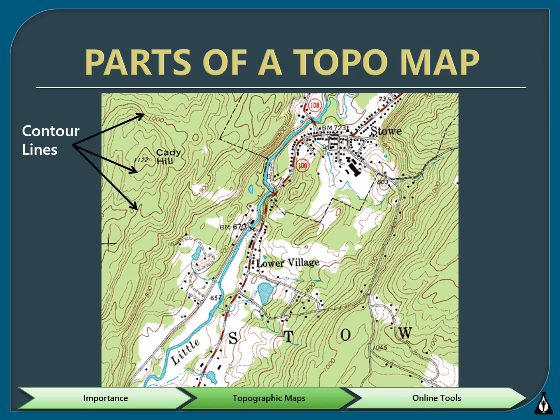The contour lines should never cross each other, and the closer together they are, that represents steeper terrain. So over here in this area, you can see all these contour lines are closer together, and over here they're closer together, so this shows a steep hillside, maybe even a cliff, whereas these areas over here are showing elevation changes further and further apart, which represents not as steep terrain.